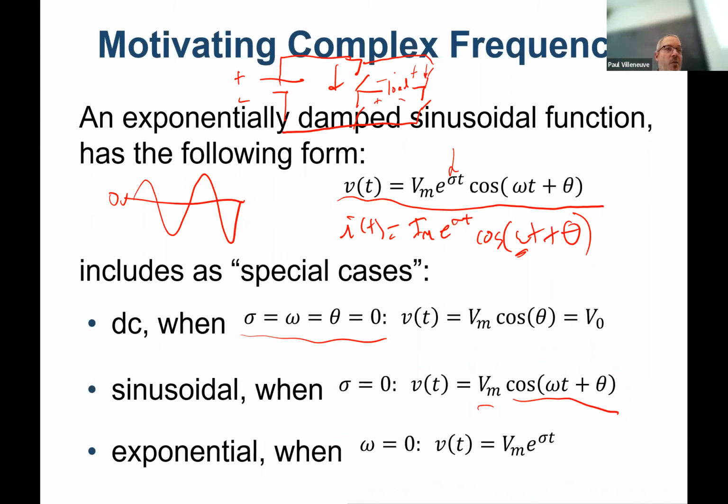Even in real world power systems, when we have a generator, and I'll show you a very simple one, we'll assume it's 3-phase. That's a real world generator, that's how it comes connected. Sometimes Y, usually Y, but it doesn't have any reference until you connect its reference point to ground. Then you provide a reference. So a sine wave doesn't necessarily need to be referenced to ground.